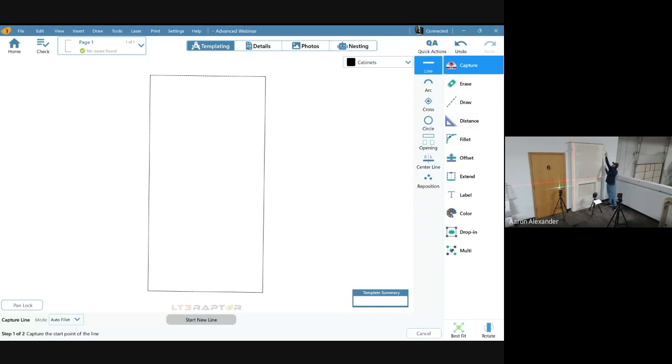So when we shoot out on these targets, it's moving those points back through space to the plane. And now when I shoot inside the firebox, it's going to pull those points out to the plane since we're behind it, right? So that's how we're flattening this thing out as we create it. It's why we can shoot in the firebox and then have targets project the edges out into space to shoot as well.